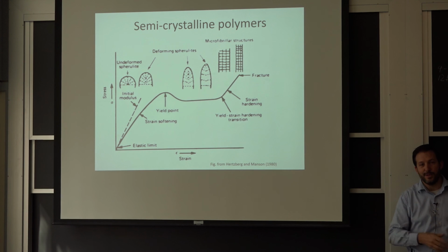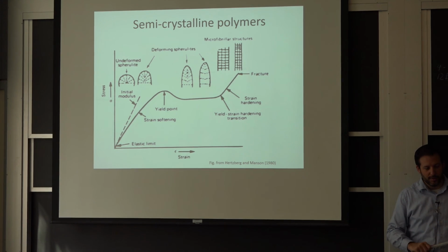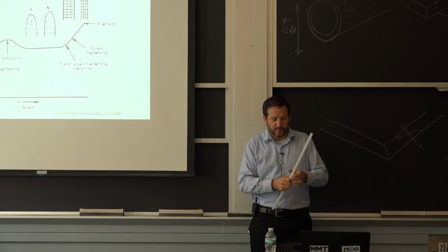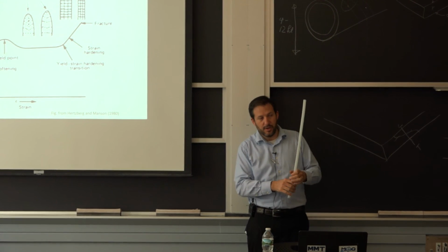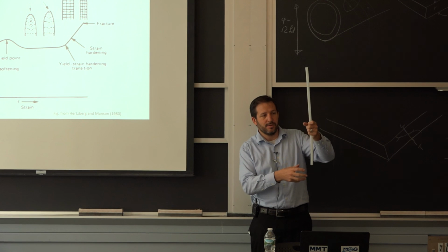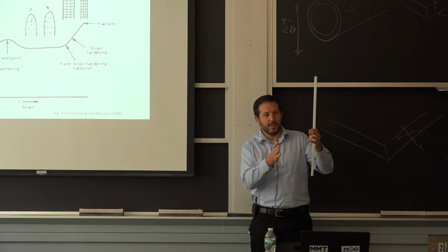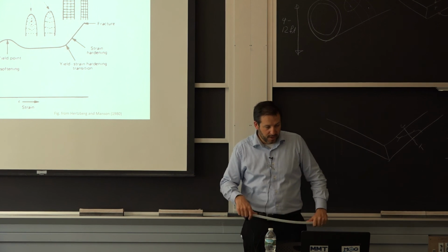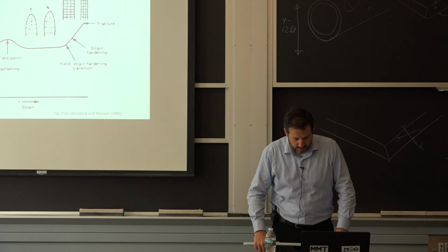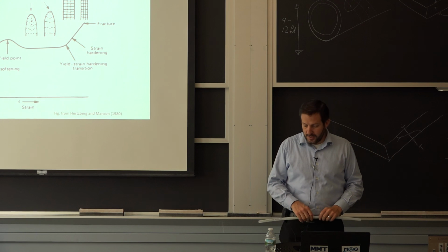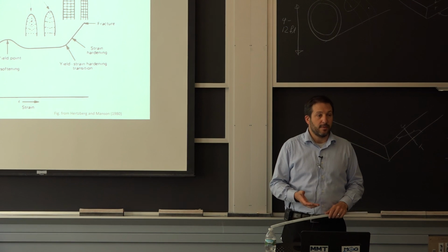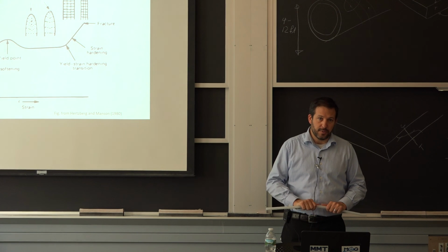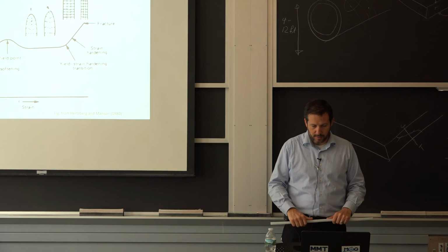The nylon in the form of the cord is becoming like a composite where you have these relatively strong fibers that are all these crystals that line up, and then you have the polymer between them. So that's done at relatively cold temperature, and that's why when you take the nylon to begin with, it's fairly soft. And it has to go through this amount of deformation before it becomes very hard.